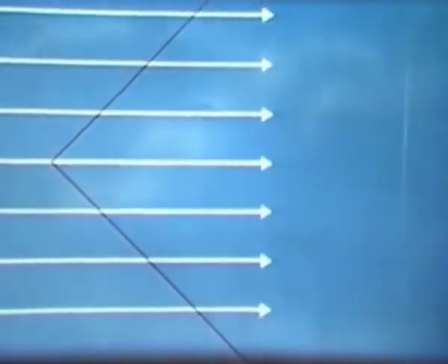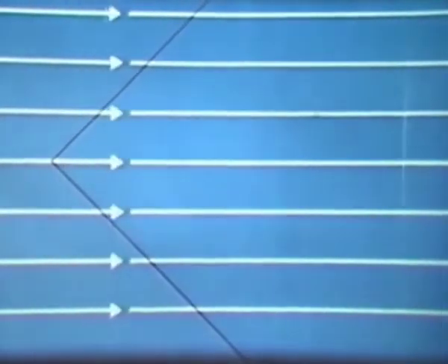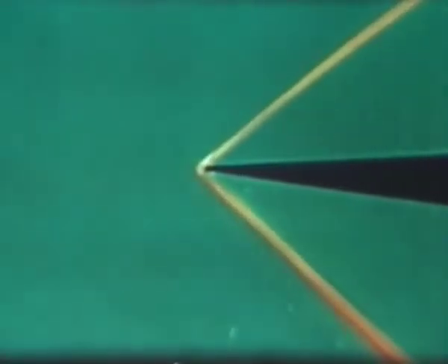Since all the disturbances coming from the point are infinitely small, the speed and direction of the airflow, shown here by white streamlines, don't change as the air passes through the Mach lines. But what if the disturbance is large? Such a disturbance is produced by a leading edge in supersonic flow. An oblique shock, the bow wave, is formed. How does the flow behave as it passes through such a shock wave?